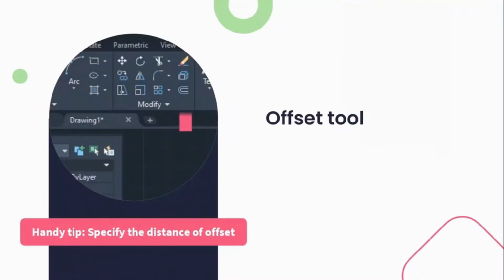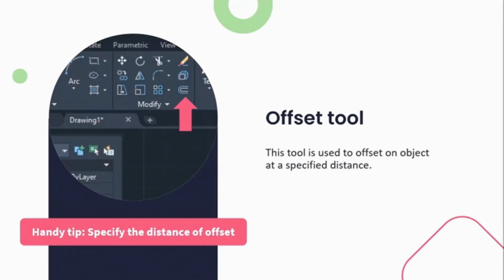Next, we have the offset tool. And as you can see highlighted by the pink arrow, that is what the icon looks like on your modify ribbon. This is quite an interesting tool, as it's a type of copy tool, but rather in the sense of distance. It offsets an object at a specific distance. Let's take a look and see how that's done.